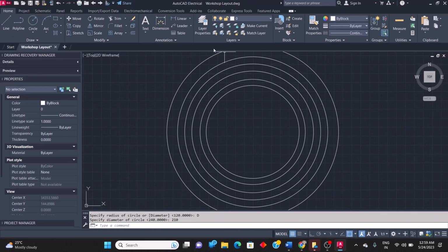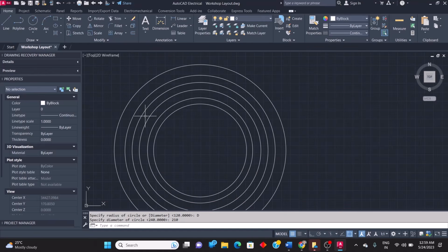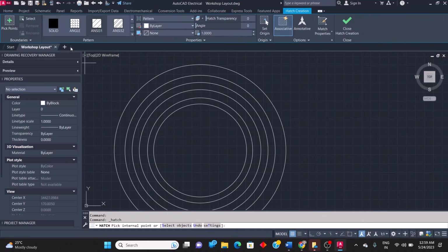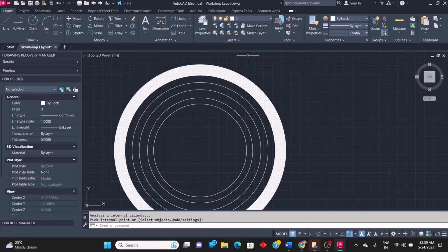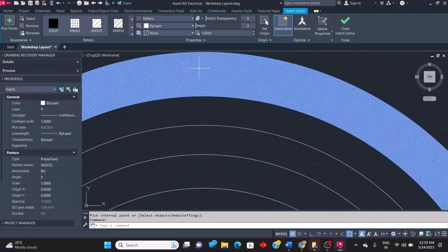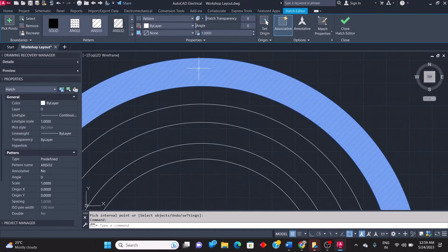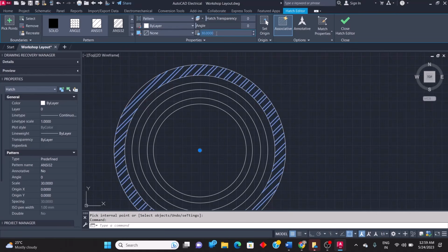Okay, here if you check, before that what we'll do, we'll assign the hatchings here. Simply we'll take the hatching and select the pattern and enter the pattern over here. If you see here it is properly inserted, but it is highly dense, so I'll take the scale to 30, or 20.